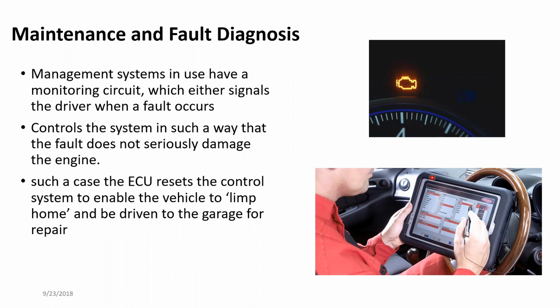So with this fault diagnostic, even though the onboard diagnostic is giving the possible scenario, the possible part that went wrong, it's not giving a 100% sure answer. There are some components interconnected. For example, ignition timing as well as the fuel system, fuel timing. For both, you need the engine load and engine RPM. So if either one of these goes wrong, the engine trouble code may not give you the direct reason. It could give you some reason related to that.